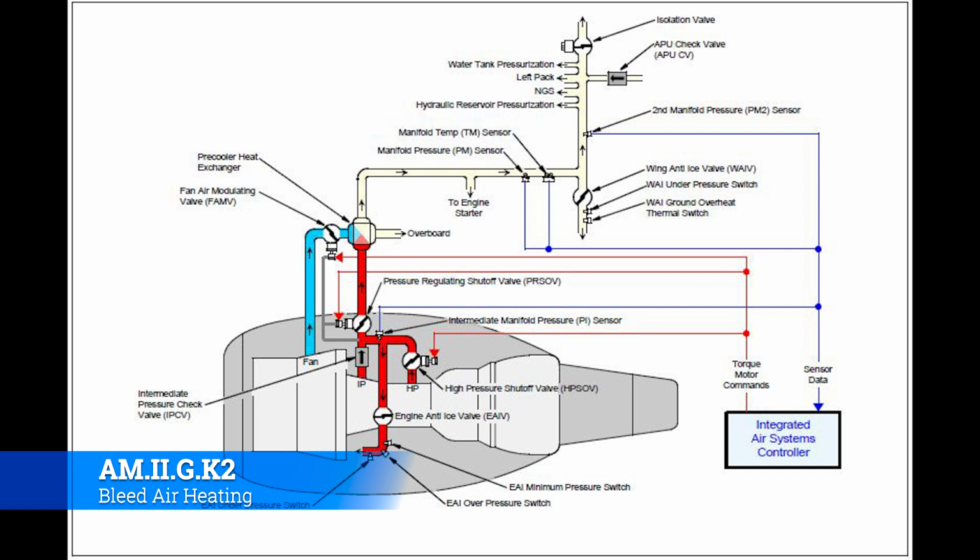That particular little tidbit's not necessarily standard across all aircraft. What is fairly standard is that if you're using bleed air for anything, you're going to be able to read it in the cockpit somewhere. Most of the aircraft that use bleed air for heating are fairly sophisticated. You're not going to run into a 172 that has bleed air heat. They have other types of heating, which is similar in a few ways, like exhaust heat exchangers and things like that, which we're going to talk about in a minute.